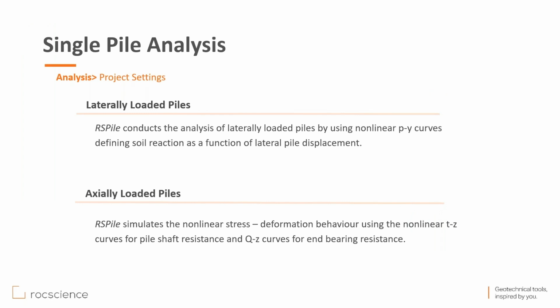modeling the behavior of laterally loaded piles by using nonlinear p-y curves, defining soil reaction as a function of lateral pile displacement. For axially loaded piles, it also simulates the nonlinear stress-deformation behavior using nonlinear t-z curves for pile shaft resistance and q-z curves for end bearing resistance.